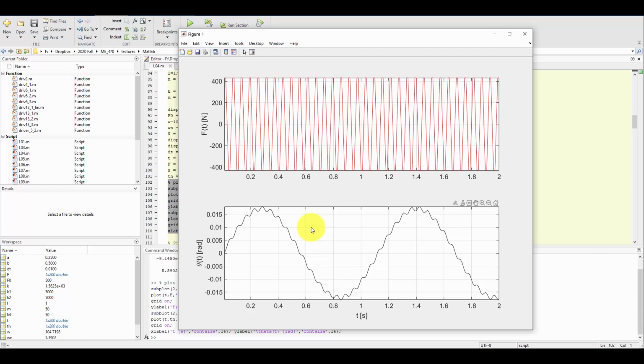So it is outside that rule of thumb difference where we would see beating. But we see in our results here 2 frequencies present, and we'll see, well, it's the natural frequency and the driving frequency, which we would expect. Now this slower frequency, so we see this peak to peak here at the slower frequency, we often call the baseband frequency. So this slower wave here from this peak to this peak would be called the baseband frequency here. Now in this case that is also the natural frequency of this mechanical system.